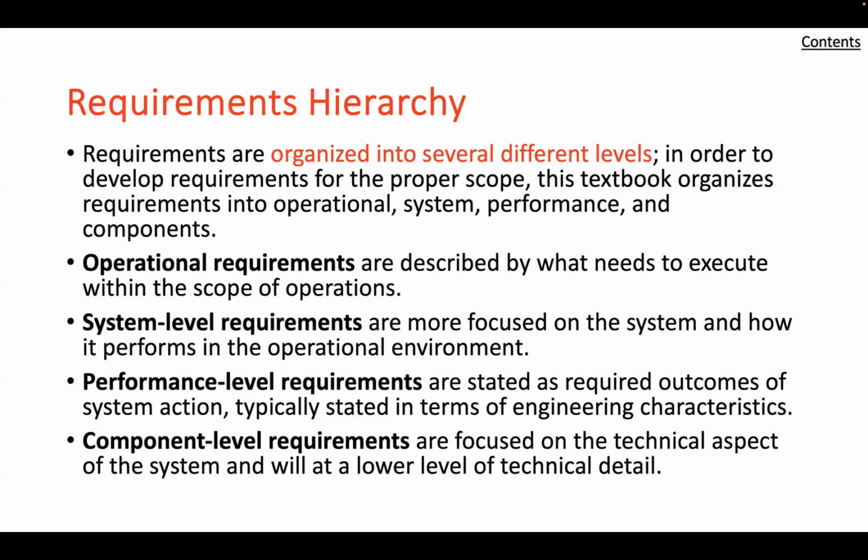Useful life is another system characteristic that is seldom stated as a requirement. To prevent early obsolescence, a system that uses high technology must be capable of periodic upgrades or modernization. To make such a process economically viable, the system must be designed with the objective in mind, making those subsystems or components that are susceptible to early obsolescence easy to modify or replace with newer technology.